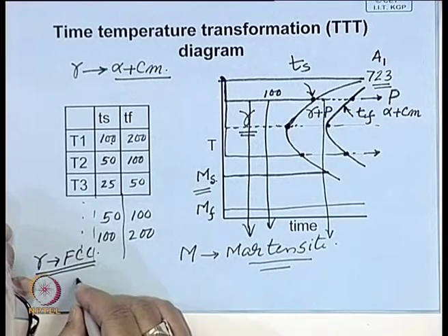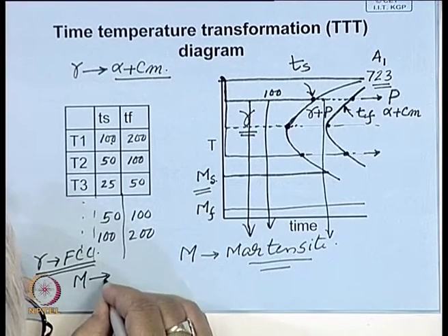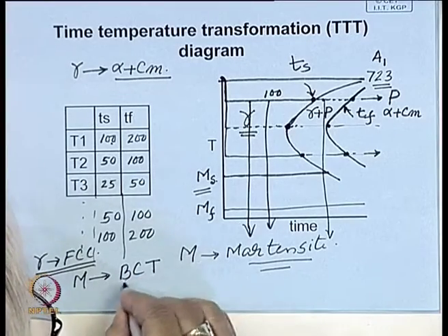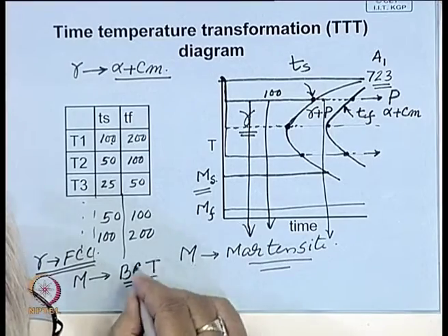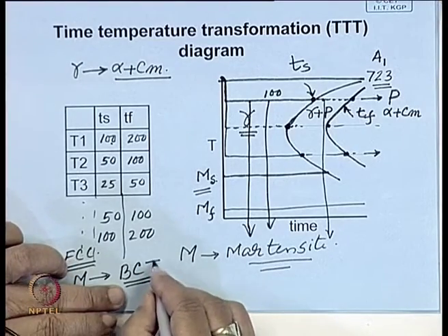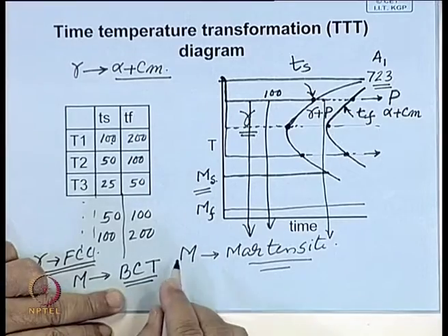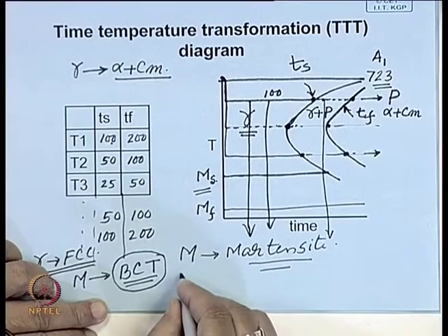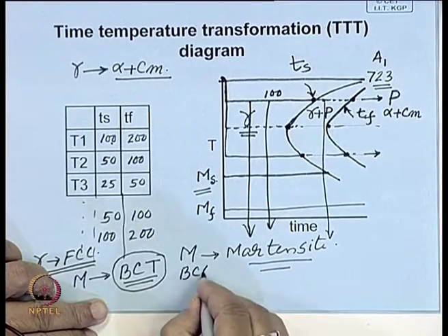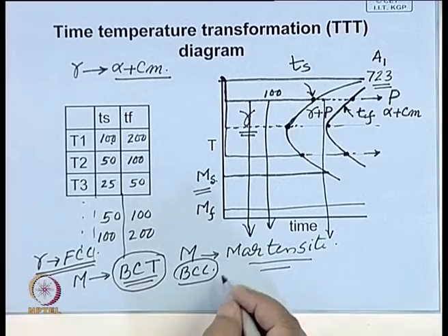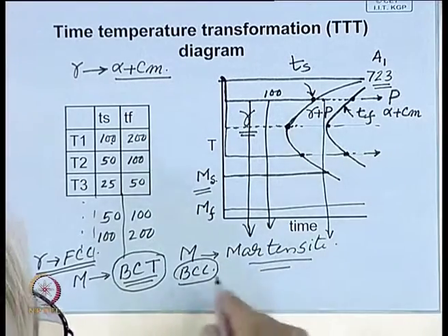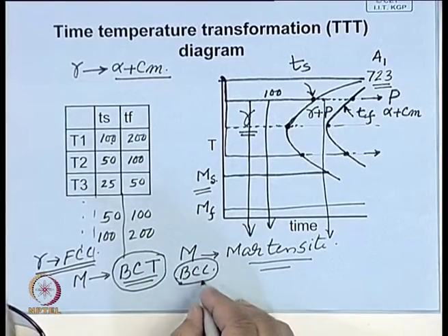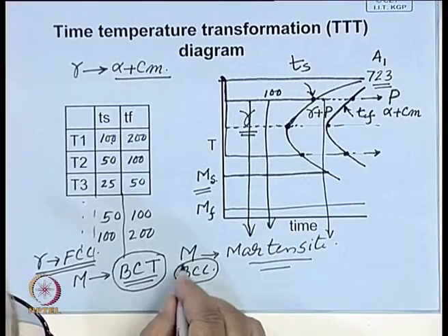and martensite is called body centered tetragonal structure. And in fact, this deviation from body centered cubic structure is very little. So, one can also assume as if it is a little distorted body centered cubic structure. We will talk about it later in other lectures as well. We will come back when we go to different subsequent chapters also. So, it is a distorted lattice.